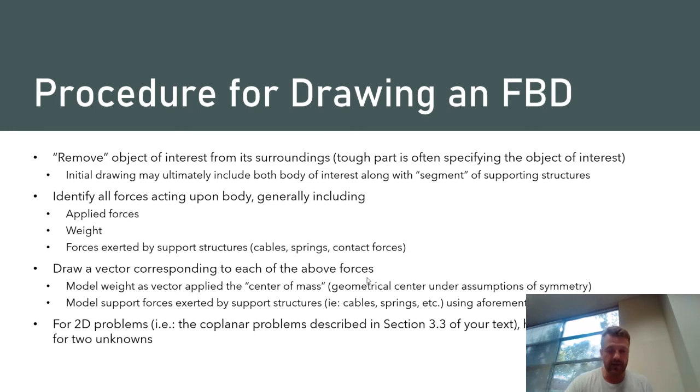And if we're dealing with a 2D problem, which is what we're going to be dealing with in section 3.3 when we move on in the actual lecture we'll be doing on Thursday, what we'll find is we have the capability to solve for two unknowns within our free body diagram. So we'll call a problem statically determinate if in our free body diagram there are only two quantities that we don't know, because we're going to be able to write two equilibrium equations.